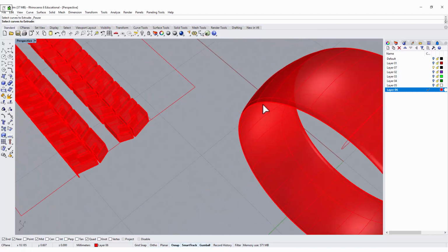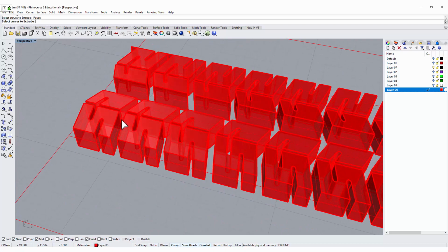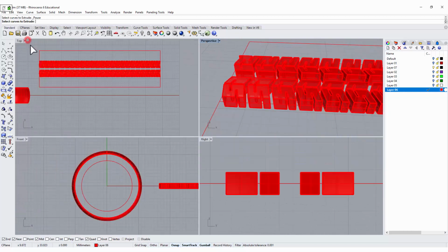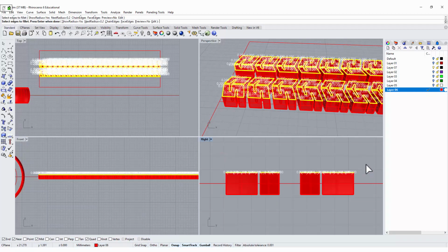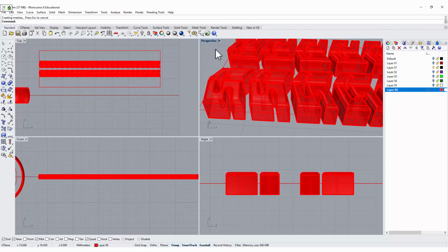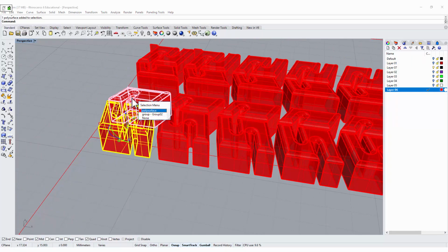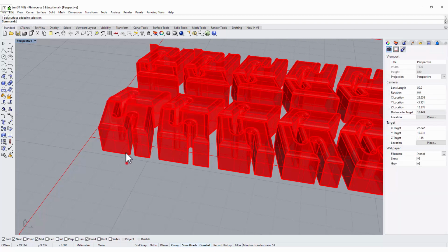Before we flow it back, we may want to do some fillet on the edges to make sure they are not too sharp first. So let's go ahead and do this. We're going to go into the front view or right view. On the top, let's use the fillet and give a little bit of radius, let's say 0.2 on all of them. Okay, so now we have a fillet, and double check by clicking on two of them and make sure that they are closed polished surfaces.